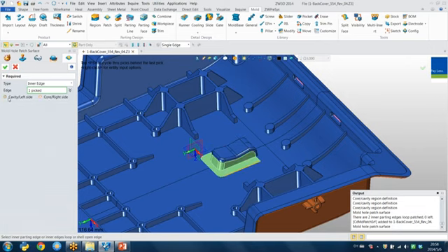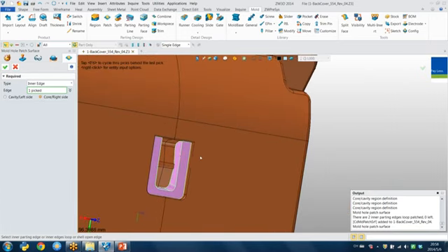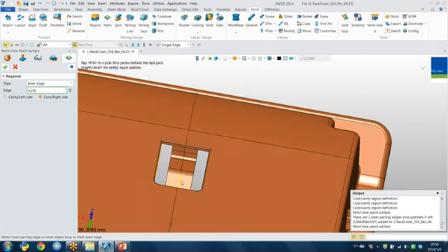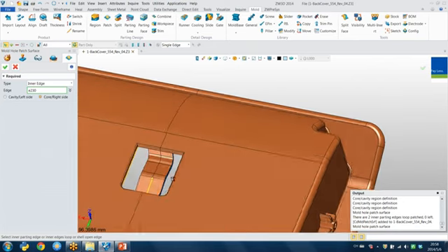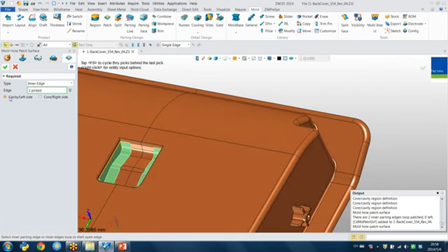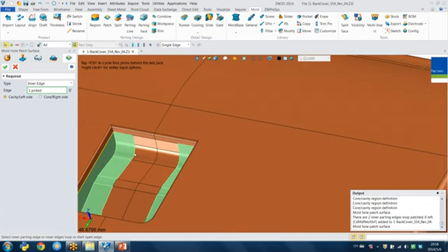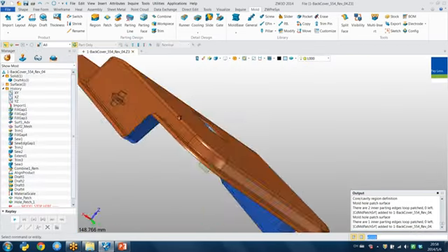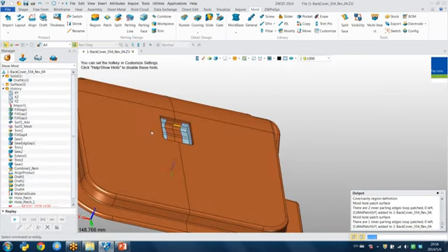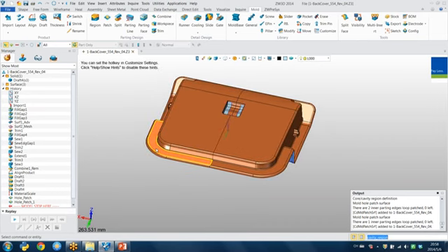So it means I can choose to correct the surface in 2 ways. Okay, so for the cavity way, for the core way. In order to get a good surface, here I need to choose the cavity because in this situation the surface is smooth. Okay, press OK.